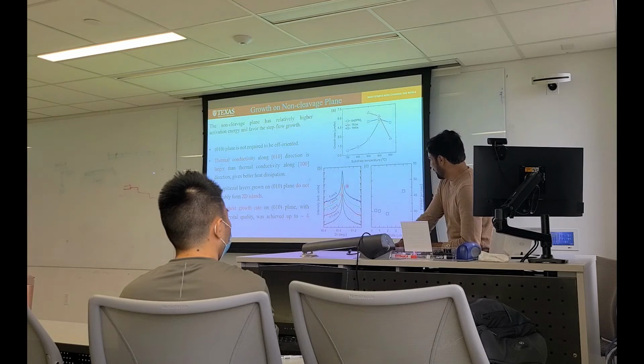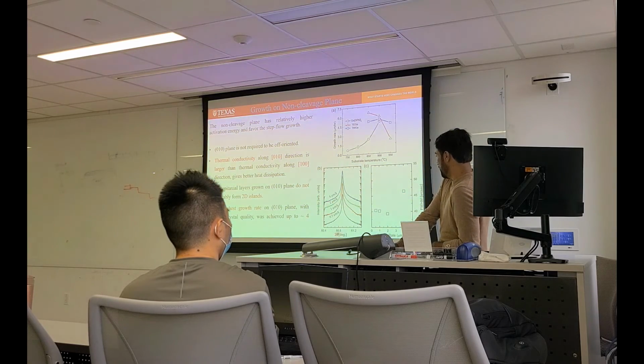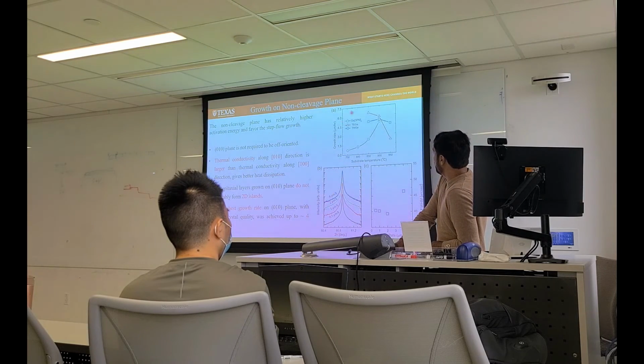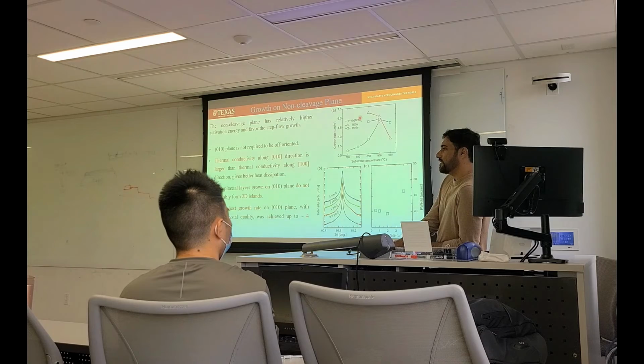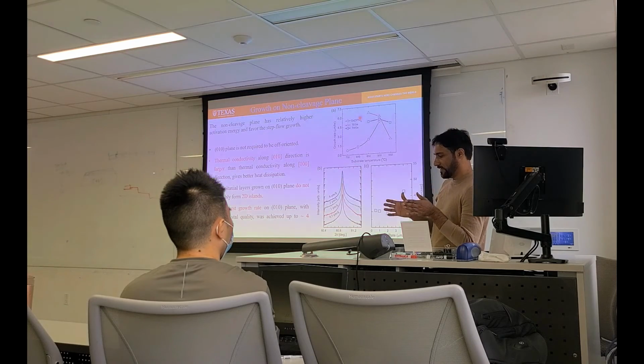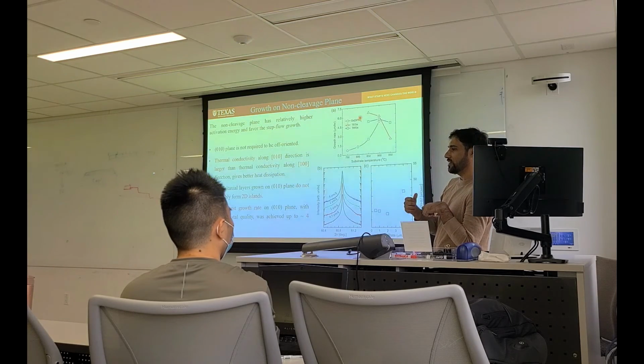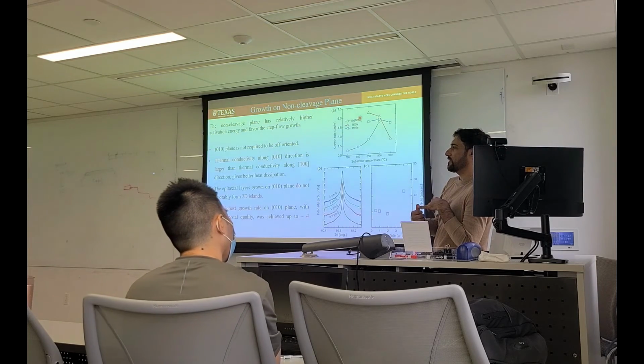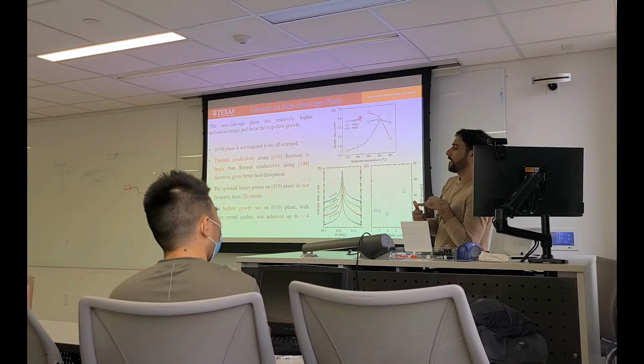So these are the full width at half maximum values. You can see there different growth rates, and this source is DPM. This source is a solid source for gallium. It is not used now. The problem was that, as I mentioned before, you have one heater to heat the bubbler to heat your MO source. For TMGa, we usually keep it at 5 degree.